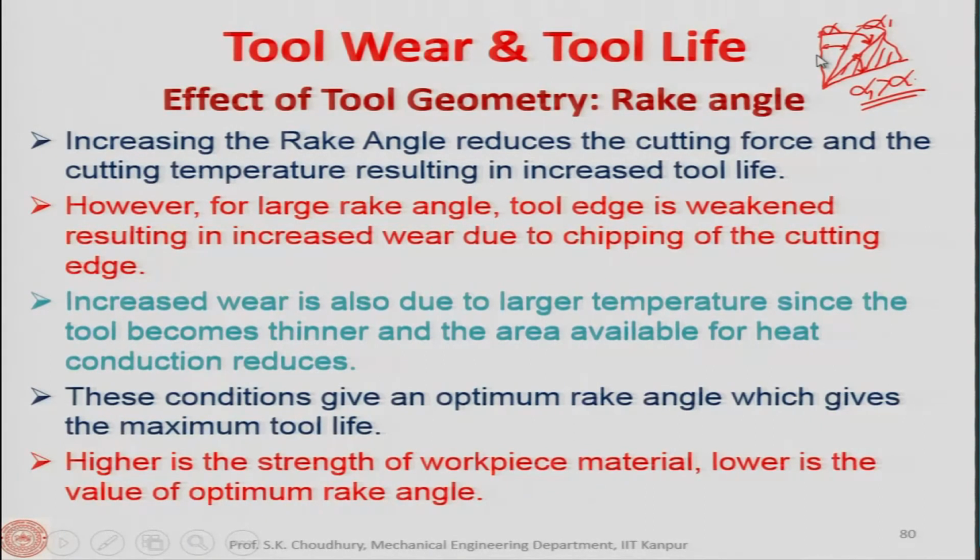So, that we have already discussed earlier also once, that since the material available for the heat conduction is less, therefore, there will be more heat accumulation, and due to that there will be more thermal deformation of the tool, and the tool wear will be more, because tool will be softened, thermally softened.